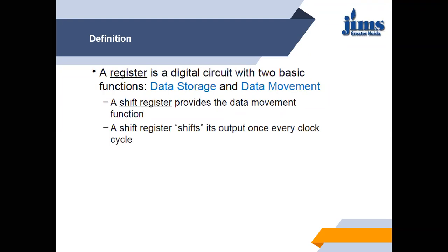When we talk about the clock cycle, we say the active clock. The clock may be level triggered when we are talking about the latches. There are two levels, logic 0 and logic 1. Any one of the logic may be active level, and we have two transitions, 0 to 1, that is positive edge triggering, and 1 to 0, that is the negative edge triggering. So we have four different ways for the triggering of the flip-flop.